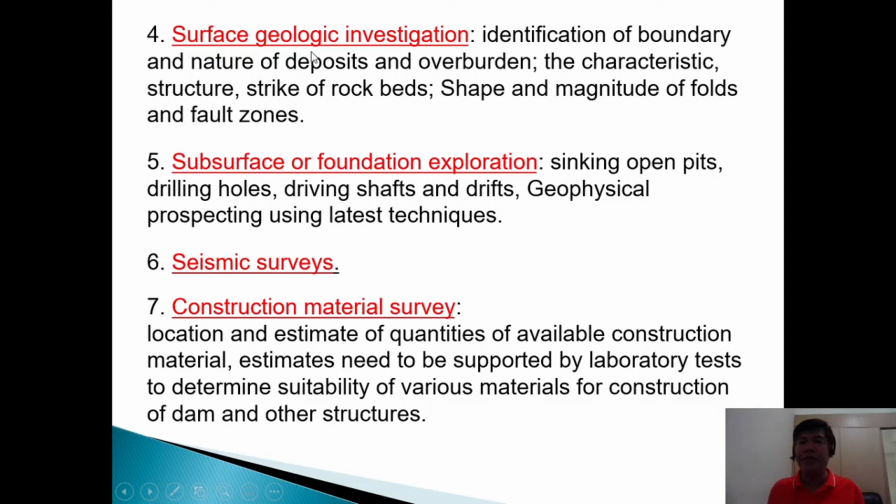Another one is surface geologic investigation. You have to identify the boundary of these deposits, the overburden, if there are different layers of the soil. There should be boring conducted to identify the characteristics and the structure of the bedrock. We also have to identify the fault zone. So all geologic parameters should be considered in this investigation.